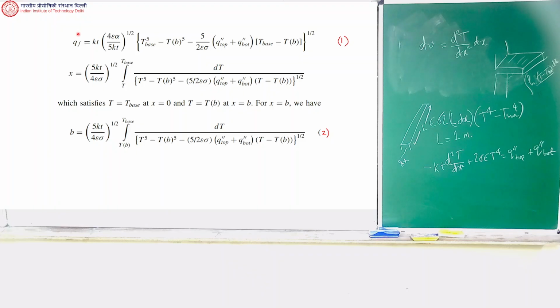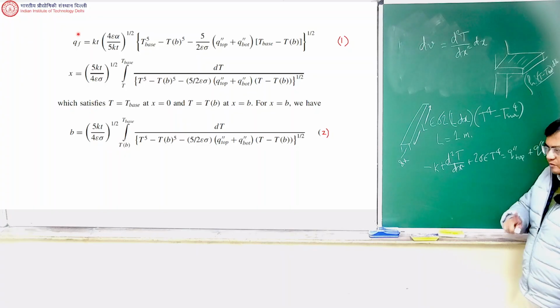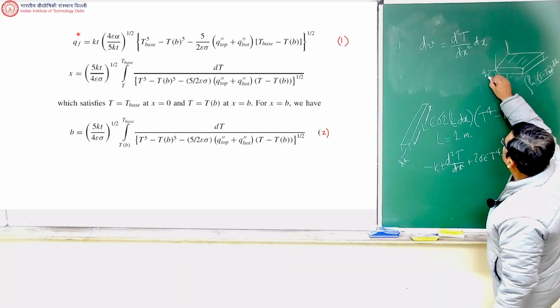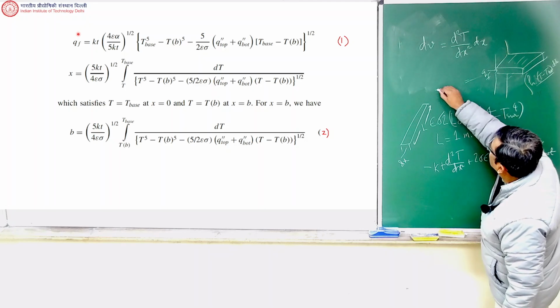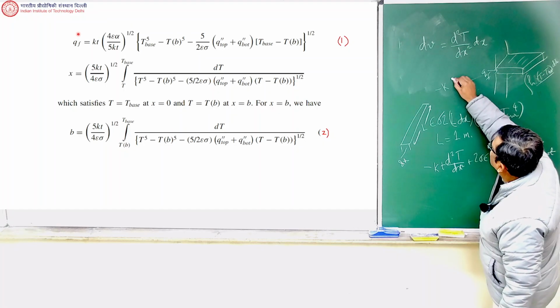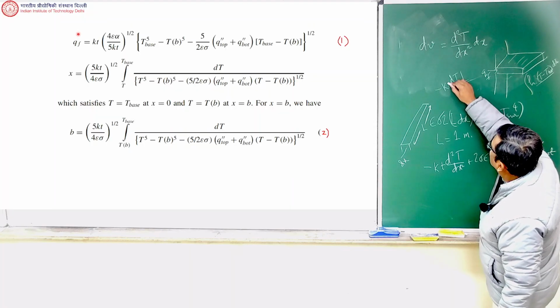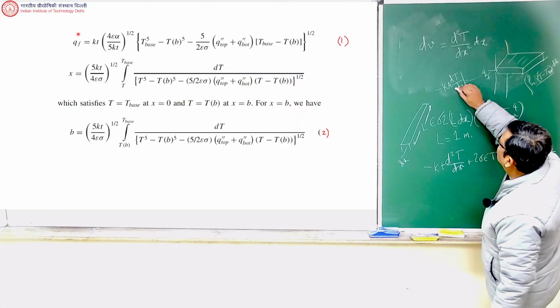Okay. Last chance. What is another way of getting Q? Correct. Okay, so that's the answer which I should have got much earlier, and from everybody, within 3 seconds. So this is QF. So obviously QF equal to minus K dT/dx times the area at the base, which we are calling AB, whatever the area is.